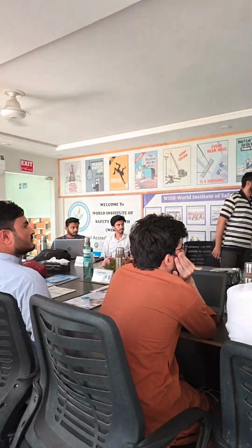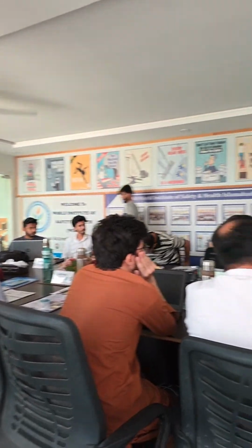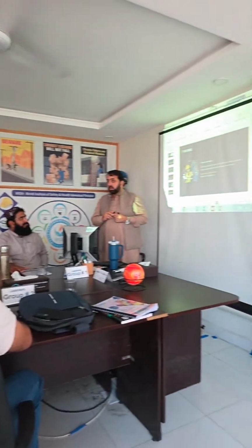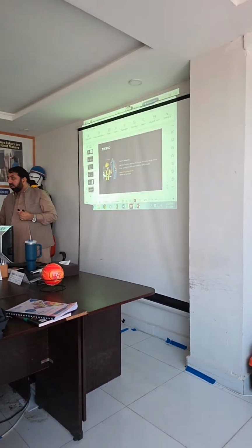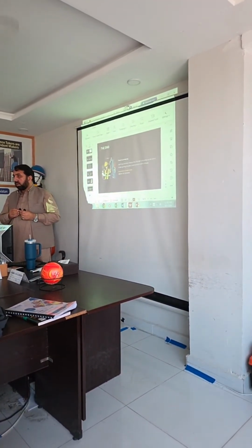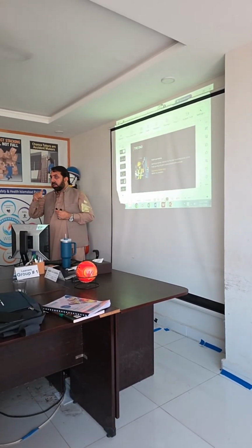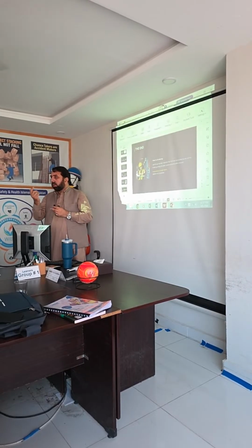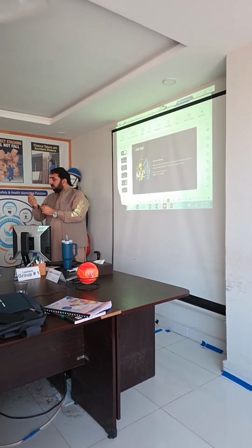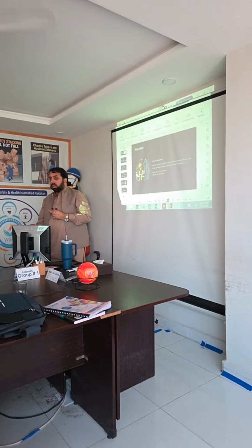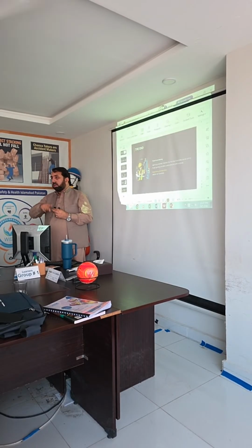Okay, there are two types. One of the big hazards I will explain to you is entanglement. You know entanglement? Why are loose clothes not allowed in the industry, especially construction or oil and gas? Because the machine is rotating, like clockwise, and you touch the machine anti-clockwise, and it catches you, like your cuff or your clothes. So it will start rotating your body also. Machine is like this, and you touch it in the opposite direction. That point is called entanglement. And due to the entanglement, the machine will rotate your whole body.